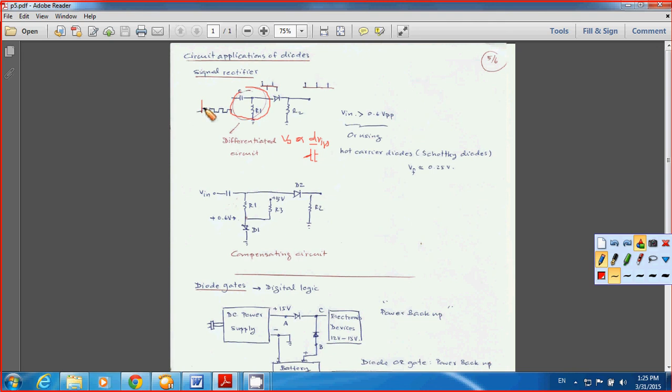But when you have this part of the square wave coming in, when you differentiate you have 0, so you don't have any signal right at this point. And for the falling edge, the slope becomes negative, so that's why you have a negative spike here. So it repeats itself. And after that, this one becomes the input of your diode here.